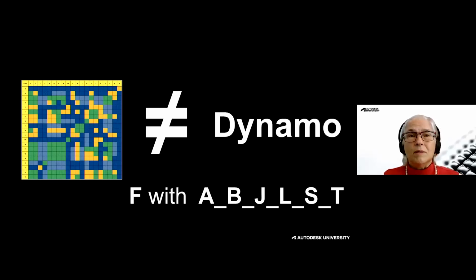The other thing we learned is about inputs in Dynamo. Dynamo can read parameters one time from Revit, and so the data transfer is one time in and hopefully one time out. There's a story to follow about that. Dynamo can receive input from an Excel file, preferably in a CSV format. It does not like comments in the data. Dynamo cannot read a matrix. Its power is in lists. So when you present it data, it's going to want to be list-like. For example, from the matrix into Dynamo, it has to translate as it shows on the screen, with F could be with A, B, J, L, S, or T, and you have to write it with the underscores.